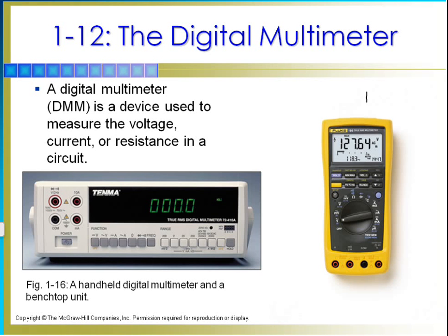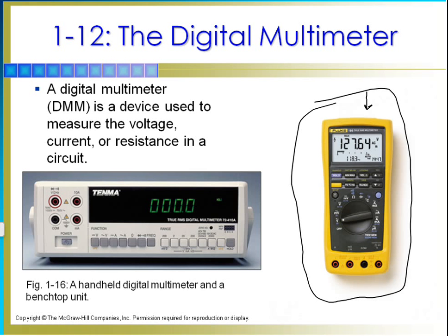The handheld, the Fluke, which is very common everywhere in the world for any kind of technician, will also do quite a few things, such as volts, millivolts. This is AC volts, millivolts, DC volts, DC millivolts, ohms. It'll measure your diodes. Looks like this one will do temperature also. Then current, amps, milliamps, microamps. So quite a bit.